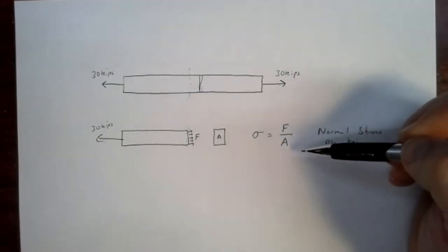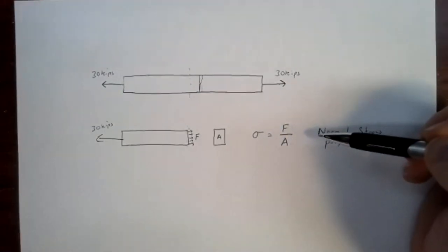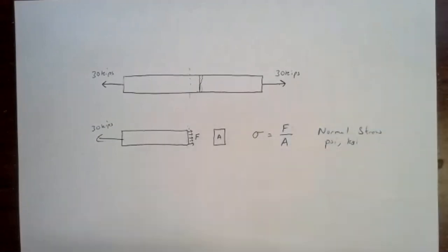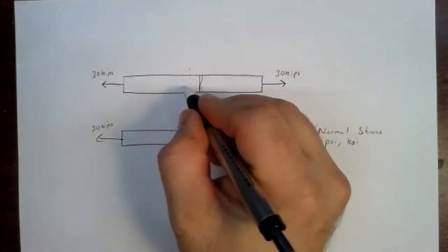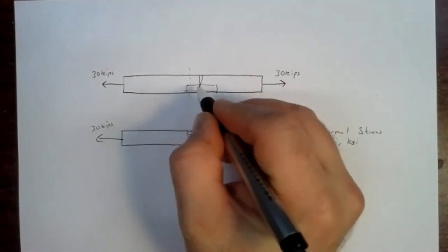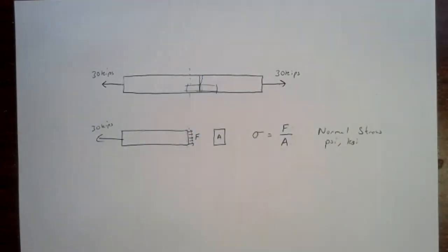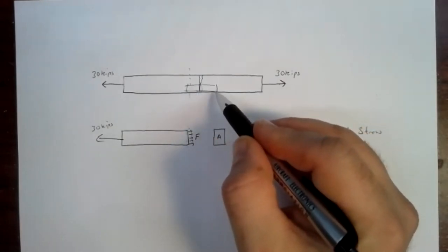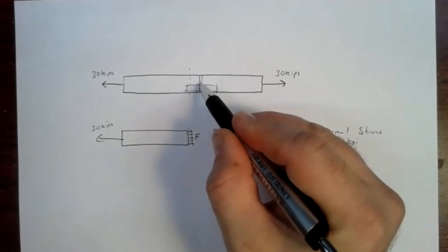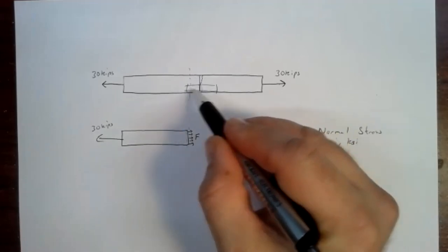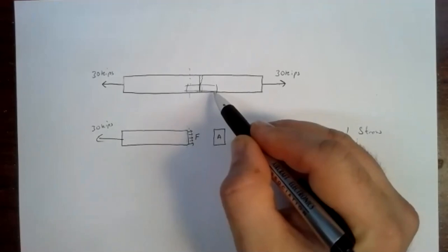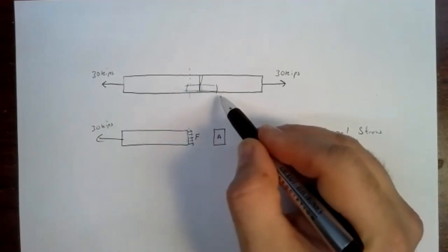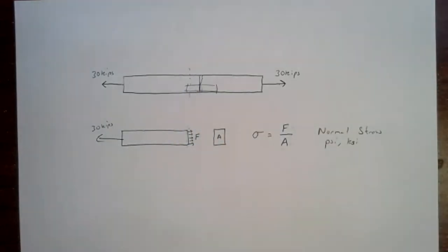One of the things that Boeing did very early in their design, trying to make sure that aircraft had a lot longer lifetime than the aircraft at the time, was to add essentially doublers, add extra material in areas that were prone to cracking, so that there was something else there that normally wouldn't be handling stress. But if the structure were to become compromised, those, what they called tear stoppers or crack stoppers, would take on that extra stress and prevent the crack from growing.